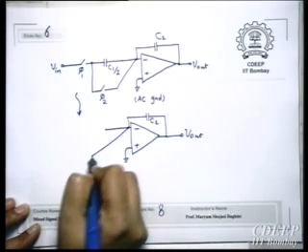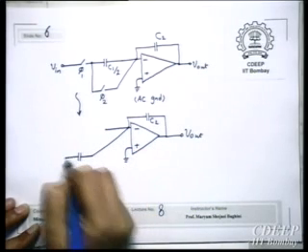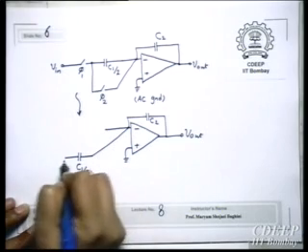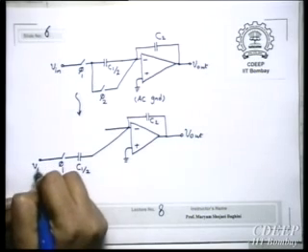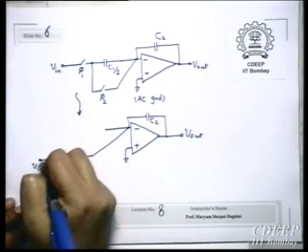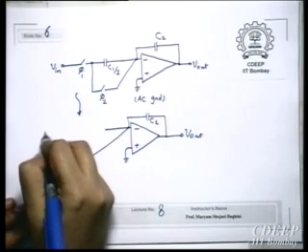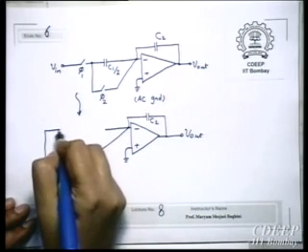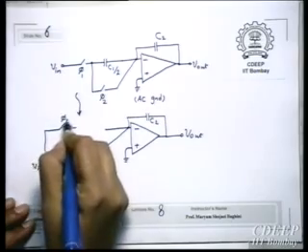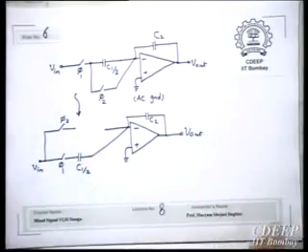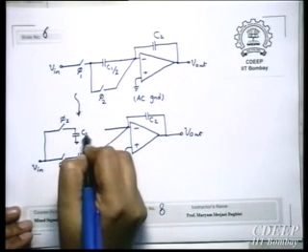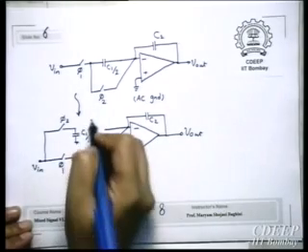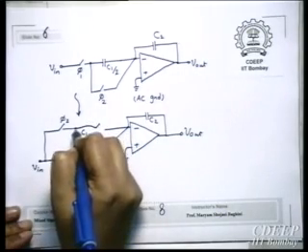So this is the component I have already, C1 upon 2 and phi 1. And this was 0. So I need to add a memory. Therefore, I need to take a sample in the previous cycle, right? So I add phi 2, therefore, it's the previous cycle. Store it on a capacitor. This is also C1 upon 2. And transfer it in phase phi 1.